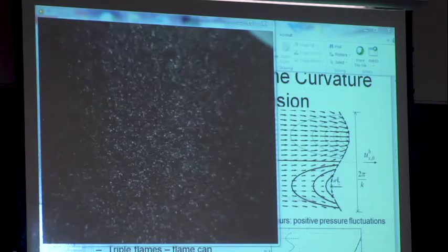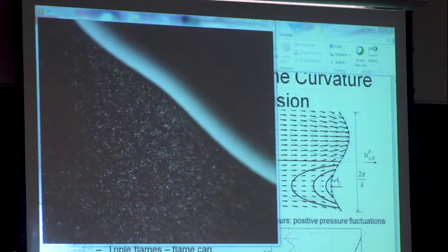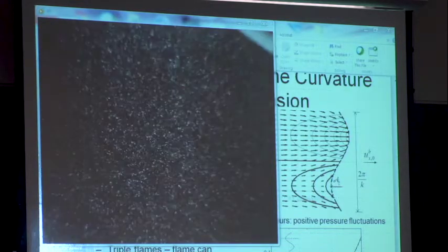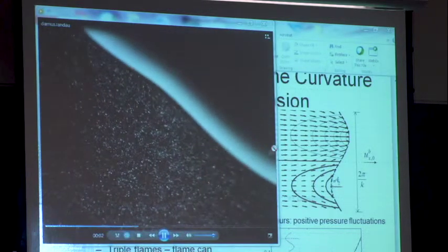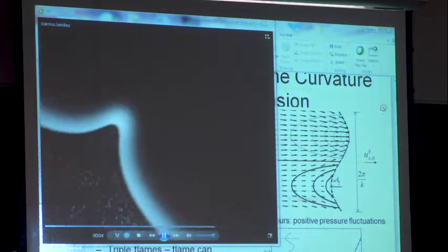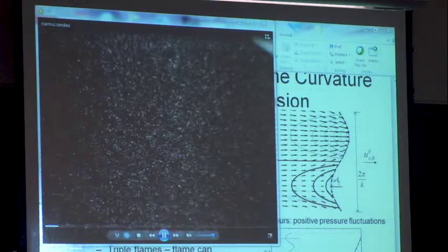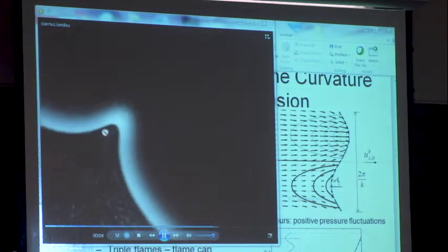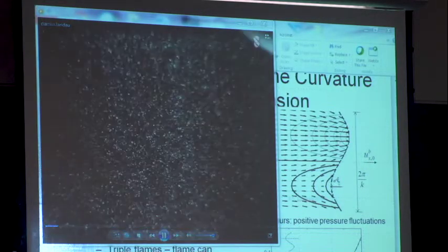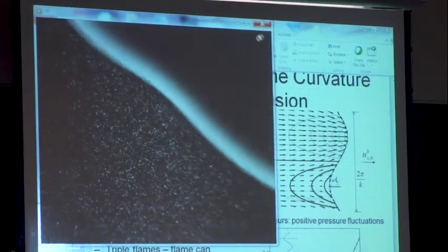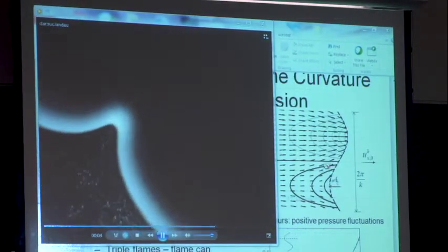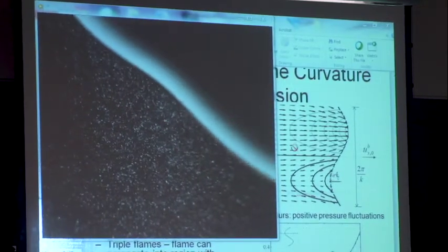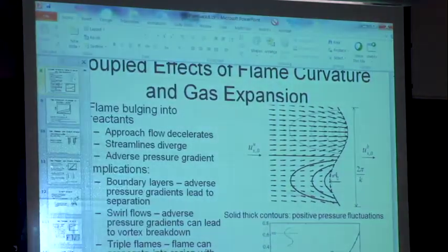Okay, never mind. Well, I wanted to show you how it's sucking the flame forward on the front end, which is what's going on over here, but the field of view isn't right. But you can clearly see what's happening here, how it induces a flow field to push that part back. But anyway, that's what leads to flame acceleration in channels, which we were just chatting about, is that the flame induces its own flow, and the flow pulls the flame ahead due to this flame instability. Okay.